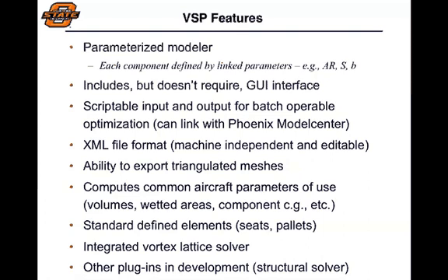Those airfoils are already predefined. You can pull those out. It also computes a lot of the common aircraft parameters that we need to use for analysis, such as the entire surface area of the vehicle, which is important to calculate drag, the planform area, which is important to calculate lift. So it allows you to calculate these directly in VSP as part of the definition.